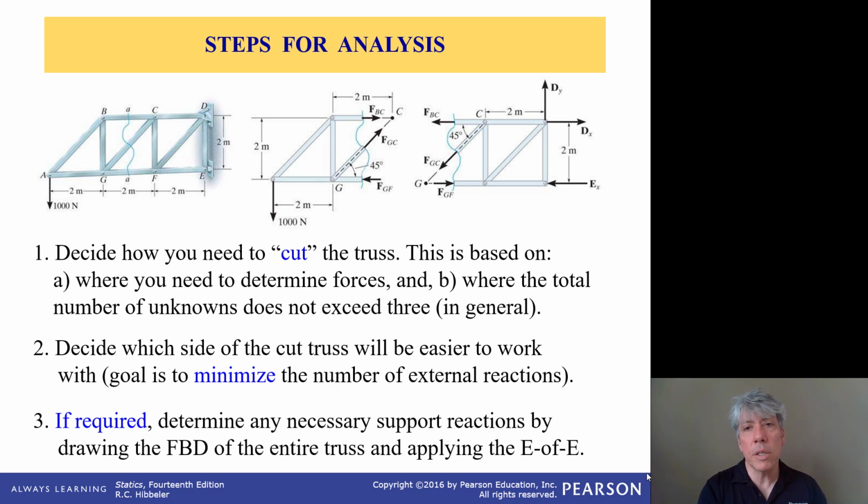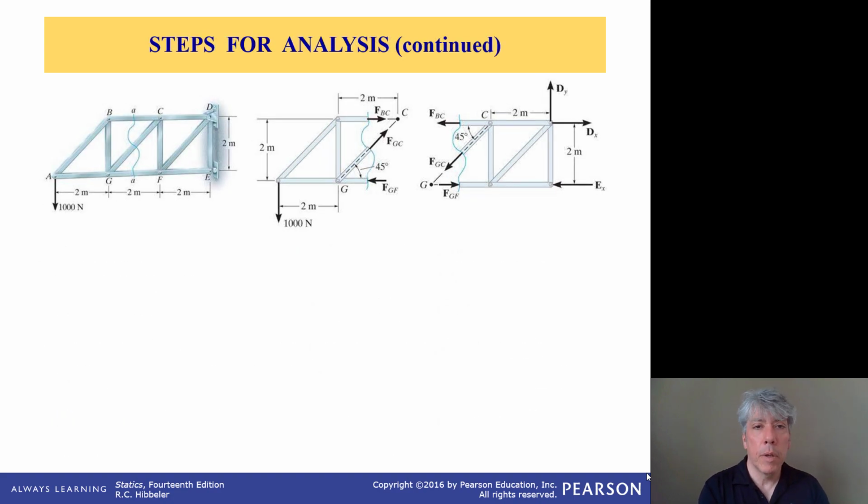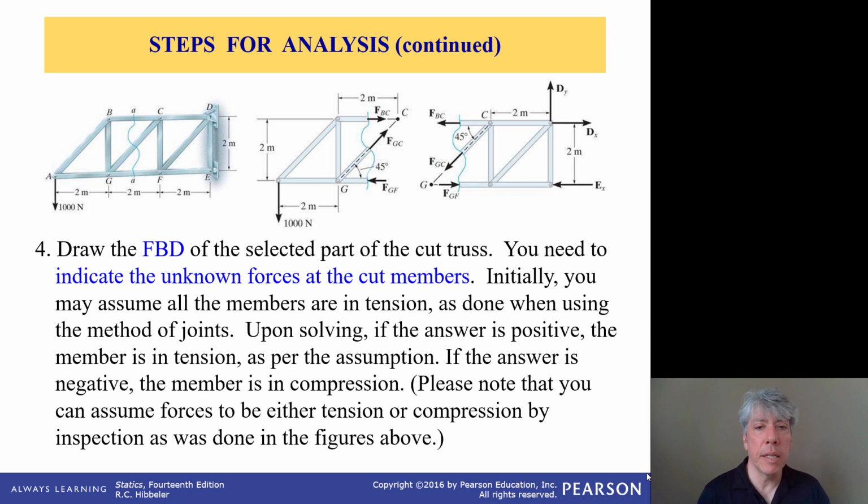Don't always go for the reactions, although I'm sort of in the habit of doing that. Sometimes you can get away without the reactions, so look for those opportunities. The final step in the analysis is to draw a free body diagram of the selected cut part, which is, of course, selected very strategically, and indicate all the unknown forces in the various cut members.